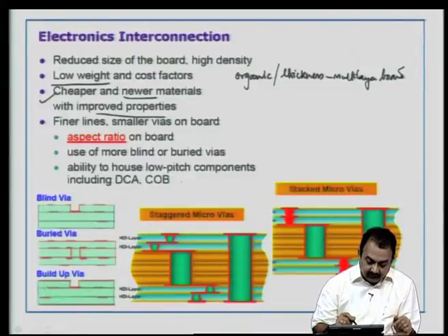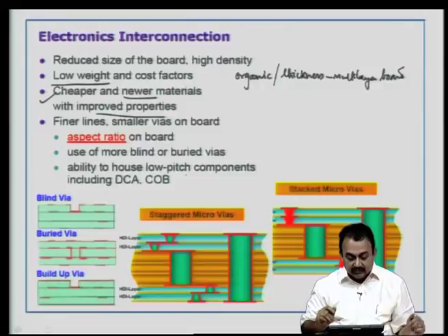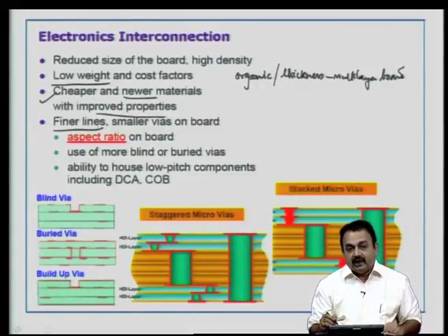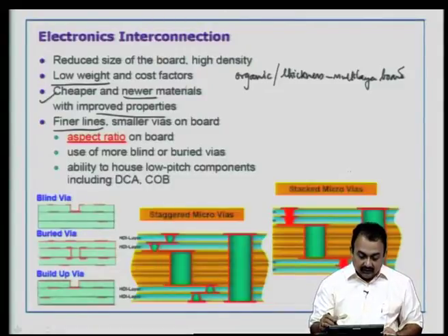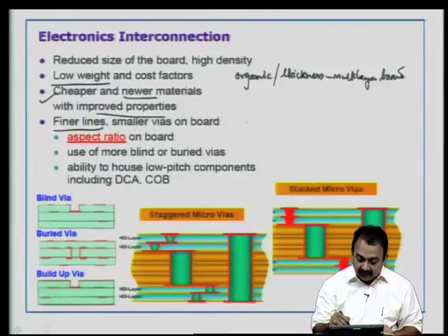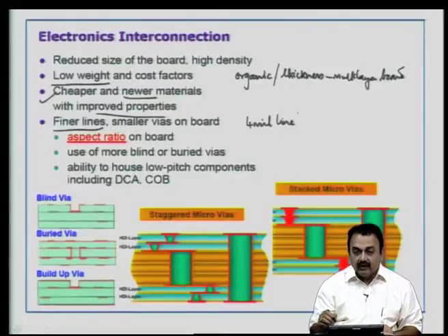As a manufacturer, you must be capable of having a line in your workshop to produce fine lines. So, if somebody asks me what is my fine line capability, for example, if I say that I can do 4 mil lines, definitely I am on the leading edge in the market today.